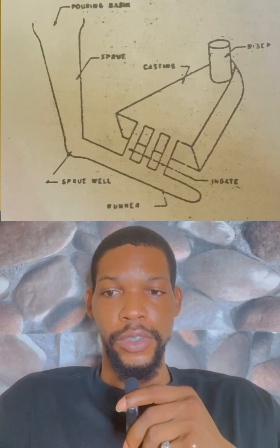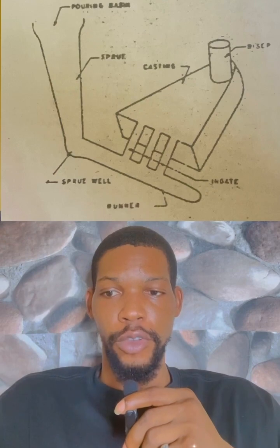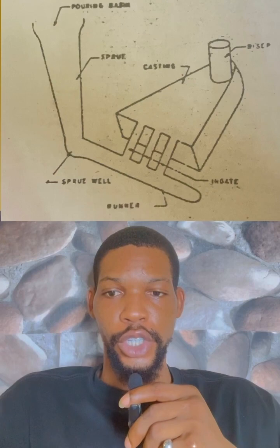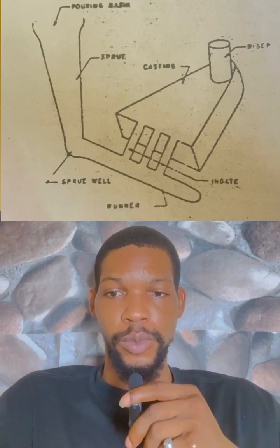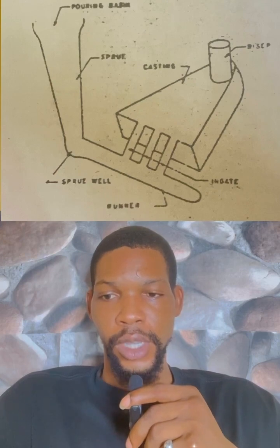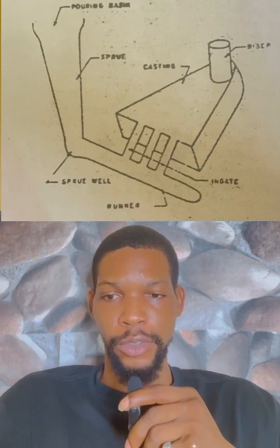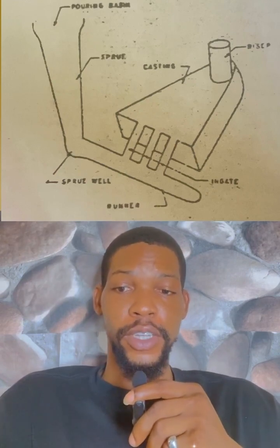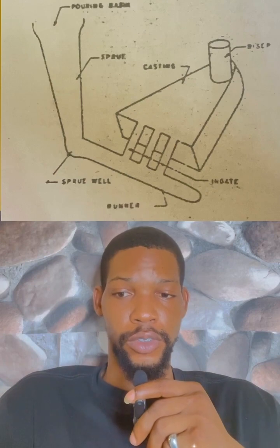The gating system must eliminate turbulence by using a well at the sprue base, avoiding sharp changes in direction, filling the mold at the lowest point, using the optimum size ingate, and filling the mold quickly while ensuring that metal flows in. The excess metal absorbed in gates and risers should be minimized. Various parts of a gating system are discussed in the following sections.